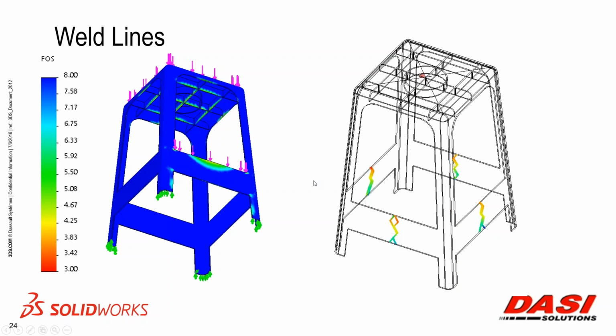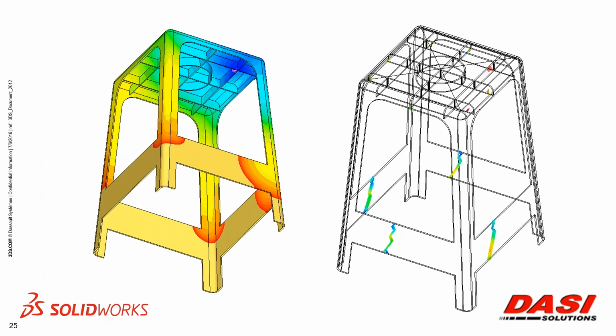Okay, so I don't want there to be high stress, of course, where there's a weld line. So what I'd like to try to do is shift the weld line around a little bit. One technique I might try to get it to move around is to change the injection location. In this case, the injection location used to be right on center. If I try moving it over to a point like here, that does shift the weld line a little bit. Okay, so you can kind of see how it's coming together down in this region if I make that injection here. Okay, so here's where that new weld line is.